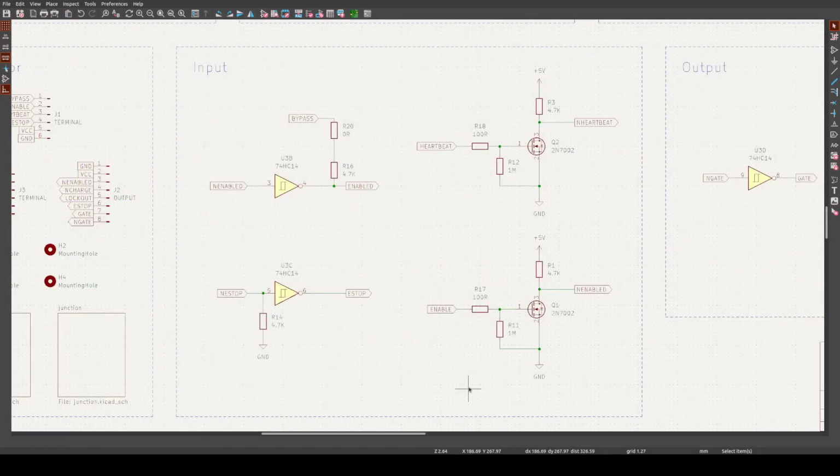These are the inputs. I used the remaining inverters and some N-channel MOSFETs for inversion when I ran out of those. When designing this and other circuits, I make sure that every output from the parallel port goes directly to the gate of a MOSFET or the high impedance input of a logic IC. This way I limit the amount of current required from the pin.